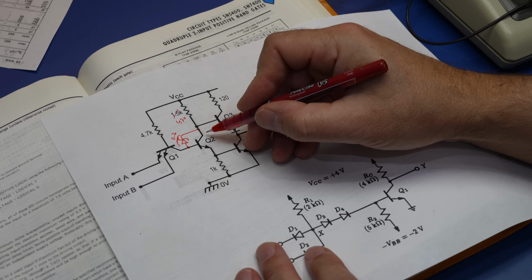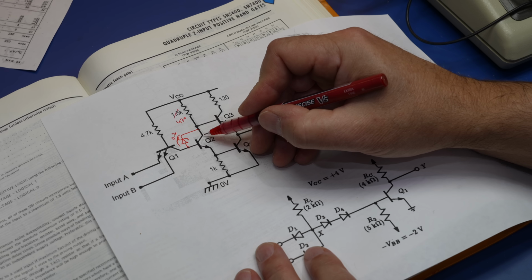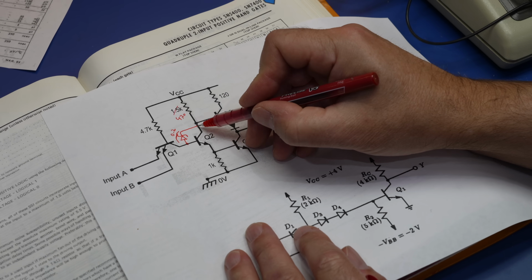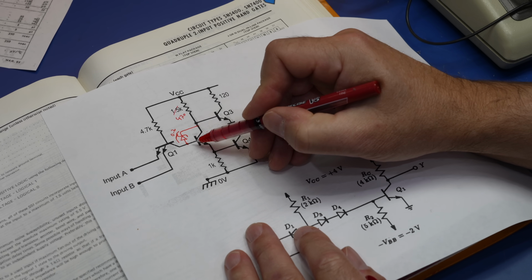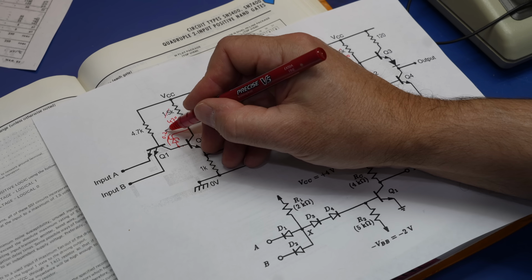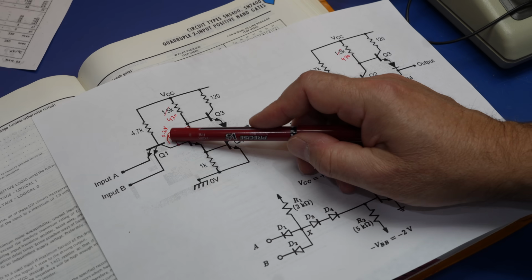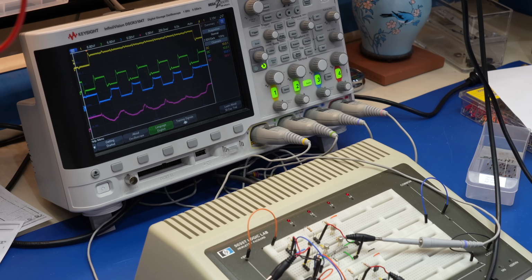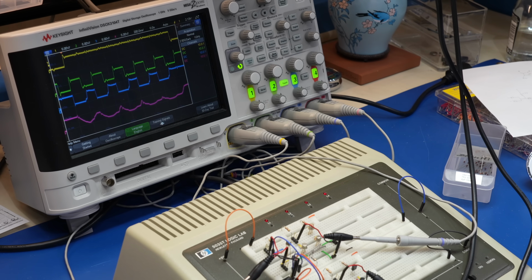Saturation is very weird. When it happens, the voltage of the base is higher than the voltage of the collector. One way to prevent it from reaching that point is to put this diode, and this will limit the differential between the base and the collector from getting too much forward bias, to 0.2 volts. And it will never go very deep into saturation. Basically, it steals electrons from the base. It just goes a little bit into saturation, so you extract the maximum out of the transistor. The TTL S gates were made first with Schottky, and then they did the LS, the low power version of it.